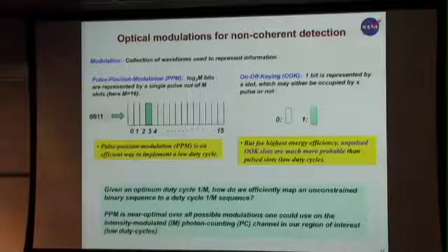Where can you put it? You can put it in one of 16 slots, which means you can encode log m, or in this case log 16, 4 bits of information. You could basically take a 4-bit sequence and put it into the slot that corresponds to its numerical value. A 4-bit binary sequence, so 0, 0, 1, 1 would be like 3, and that would be this pulse right here. As I say, PPM is pretty near optimal.